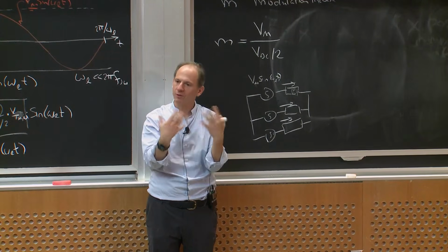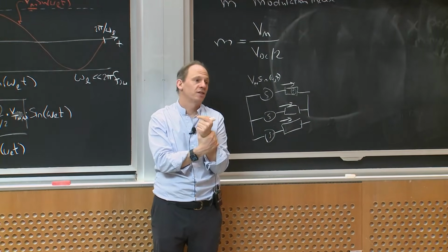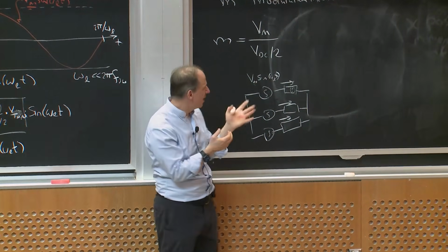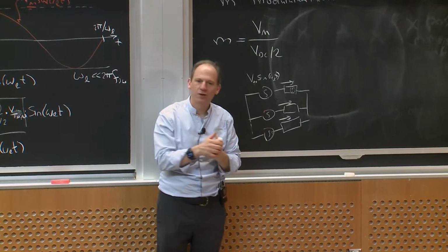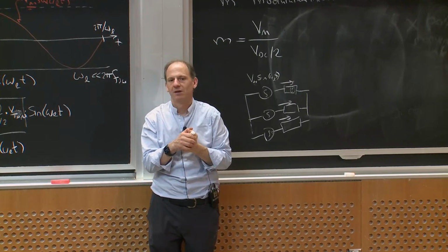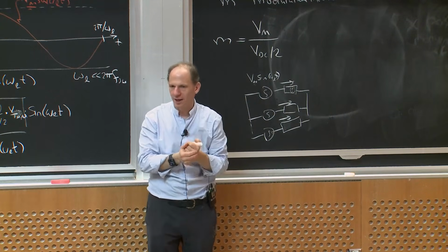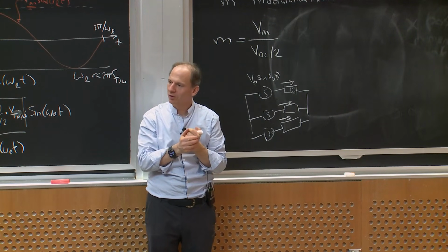I'm going to have low frequency harmonic content in my output. So the question is, is there a way you can extend the range over which you can generate, if you will, pure sine waves at the output of your motor and generate no low frequency, like line frequency, harmonic content? And the answer is there's a trick for doing this.